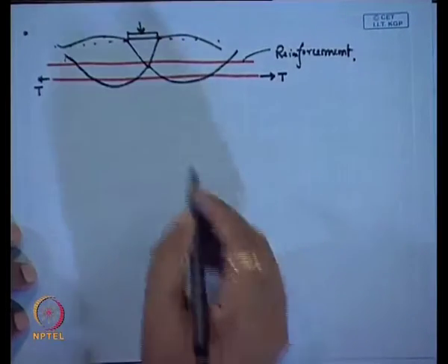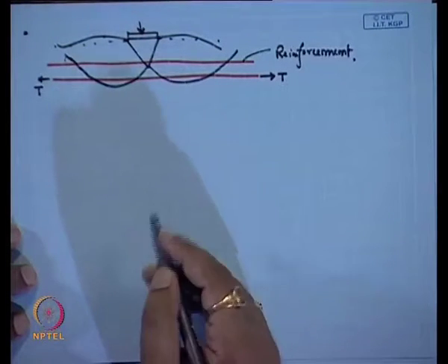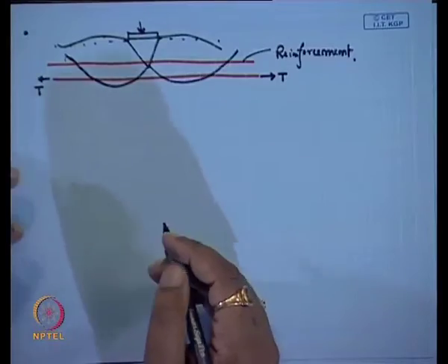There is internal friction within the soil and the geosynthetic or reinforcement, and because of that, as if we are holding this reinforcement on both sides, in the center region, because of the soil foundation pressure, this reinforcement is moving downward. We are holding the reinforcement because of the sufficient anchorage length we are giving. So the soil is holding the reinforcement on both sides, and the center one is moving downwards. Because of that, the reinforcement will be subject to a tension.